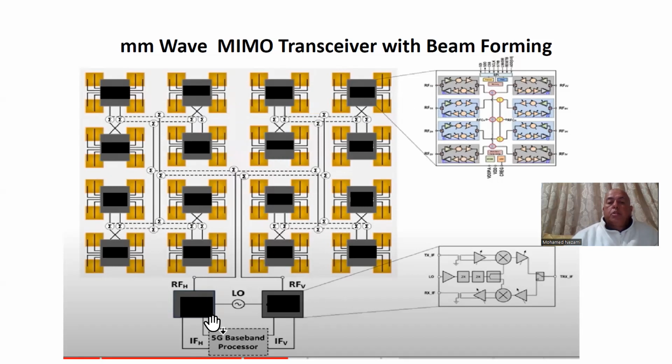And then we have an up converter section that took the 3.5 gigahertz from the DAC and up converted to 28 gigahertz and then split that signal in the transmit path. You split that signal, of course, for both horizontal and vertical to distribute to the 16. And that's this chip here, of course. That's the block diagram of the chip. So one polarization is color coded with the blue here, and the outer two are for the other polarization. And this is the up converter path and the uplink and downlink in these chips.